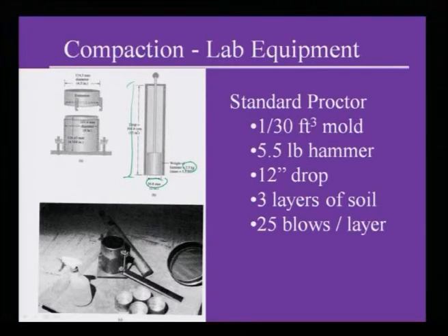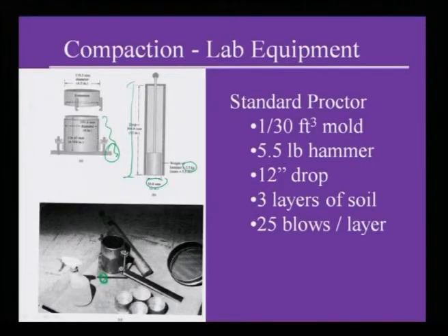There are two molds, one is your standard Proctor mold, the other is your modified Proctor mold, and this Proctor mold has a base plate. If you look here, this is your base plate. With this base plate, the standard Proctor mold has a diameter of 10 centimeter and a height of 11 centimeter, almost 10 by 10 centimeter you can say. The mold is attached to the base.